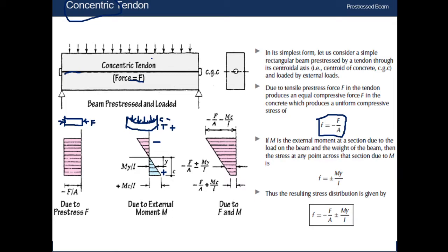Then after that, when it will be subjected to working load or service loads, what will happen? It will bend in this pattern. It will go through this pattern of bending. In this pattern of bending, due to the service load, we will be able to see compression in the topmost fiber, which is indicated by negative, and tension in the bottom fiber, which is generally indicated by positive.